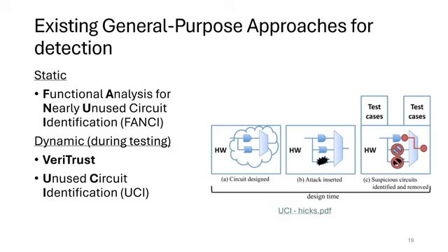So these are some existing general purpose approaches, which all three of these listed are basically just a scan for rare circuitry or things that aren't really activated during testing. Why is that not being activated during testing, since a test bench is supposed to iterate over all of the possible uses of hardware? A counter that doesn't get used, or a signal that is seemingly benign but never changes, can be a red flag for further investigation.